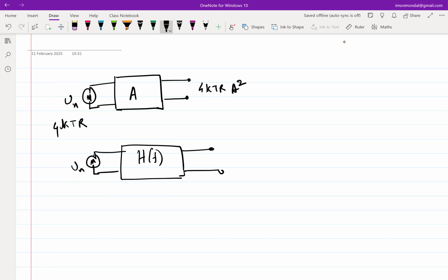Put a sinusoid at the input and shift the phase. Yeah, it's basically a delay. Right? Phase is equivalent to a delay to a sinusoid. So when I say the phase is frequency dependent, it essentially means that at a certain frequency it gives so much delay, in another frequency it gives a different delay. Right? That's all it means, right?